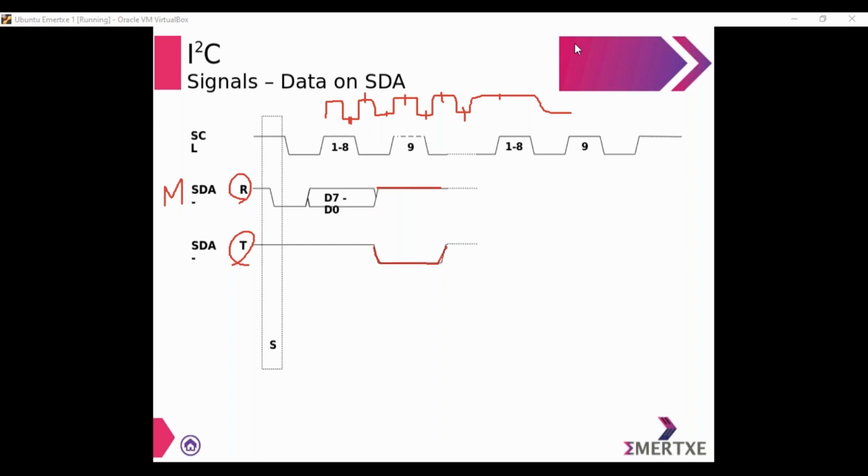Now RTC transmits the data from the second register in the first 8 clock pulses. At the low level, RTC transmits 1 bit. At the high level, the master receives that 1 bit. Again, at the low level, RTC transmits 1 bit, and at the high level, the master receives 1 more bit.